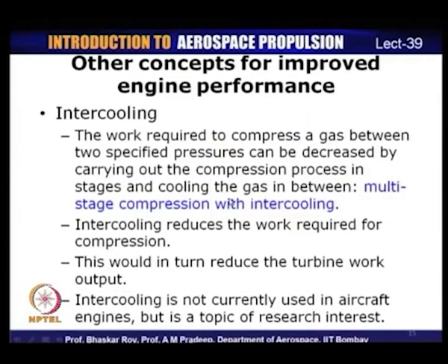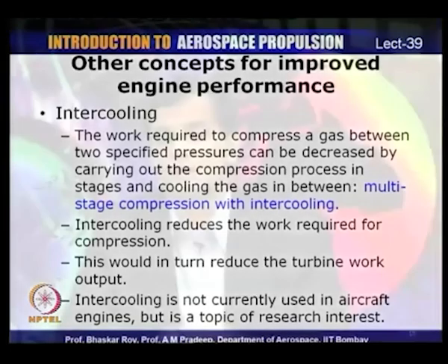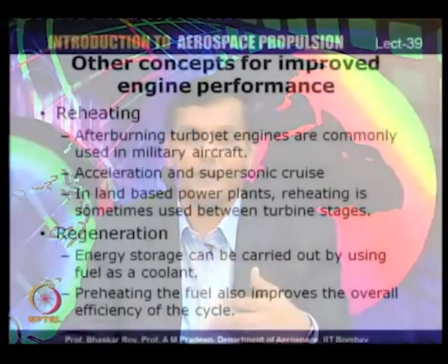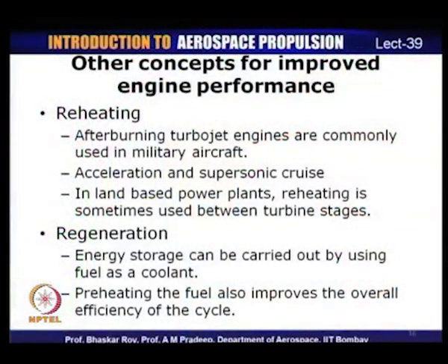Now, intercooling basically reduces the work required for compression, and in turn it reduces the turbine work as well. And as I mentioned, intercooling is not really being used in aircraft engines as of now, but it is a topic of extensive research interest, because there are a lot of performance benefits that one can gain by employing intercooling. And therefore, there is a lot of research currently being undertaken on trying to apply intercooling between compression stages in an aircraft engine application. Reheating, on the other hand, has been used for a long time now in both land based as well as in aircraft engines, and its benefits are already being seen.